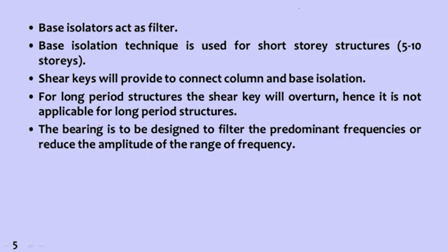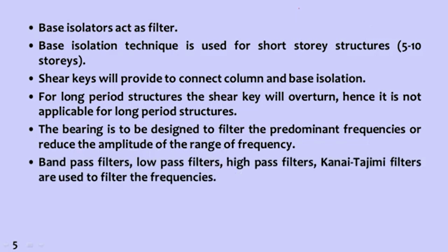So the bearing is to be designed to filter the predominant frequencies or to reduce the amplitude of the range of frequencies. So band pass filters, low pass filters, high pass filters we use. There are special filters called Kanai-Tajimi filters used to filter these frequencies. So we'll see a cartoon of how this base isolation works.